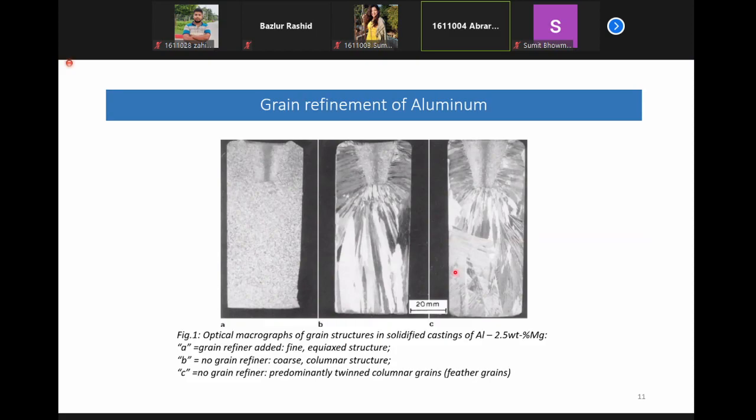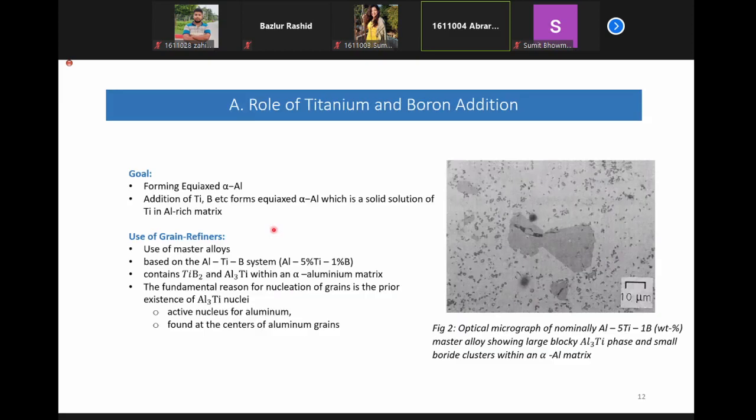Firstly, grain refining is incredibly essential in the case of aluminum alloy production, because if you look at these two, these are situations where we didn't add grain refiner to the system, so we get a very large fraction of columnar grains with very bad anisotropic properties, whereas here we added the proper amount of grain refiner and achieved almost complete equiaxed grain structures, which have superior mechanical properties.